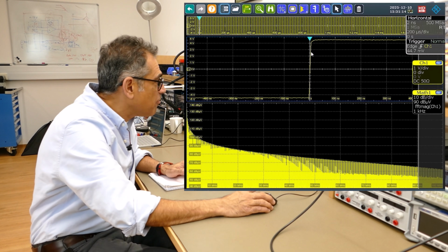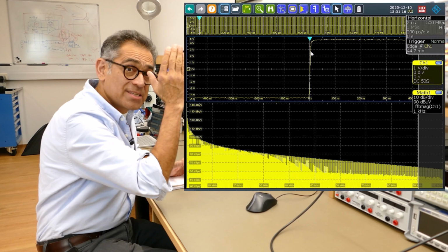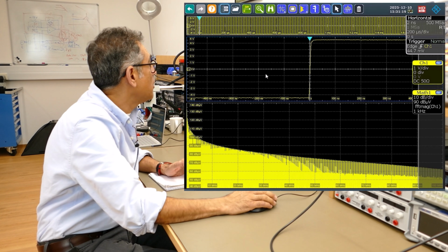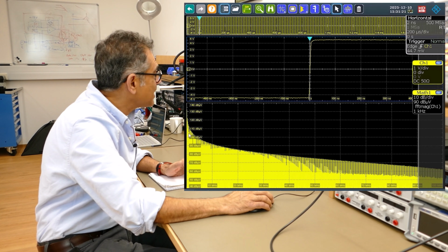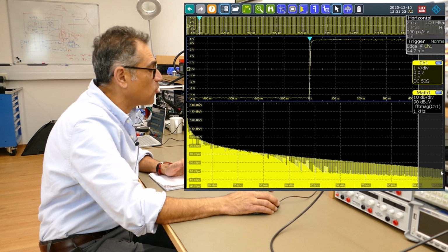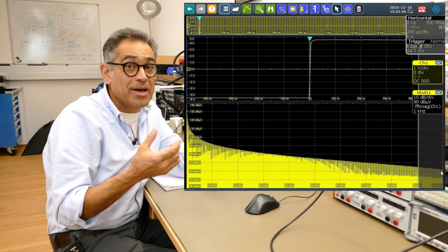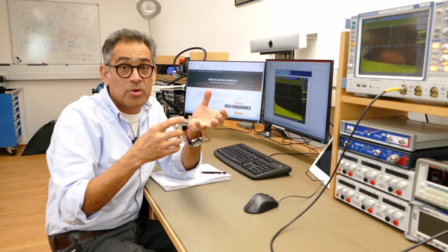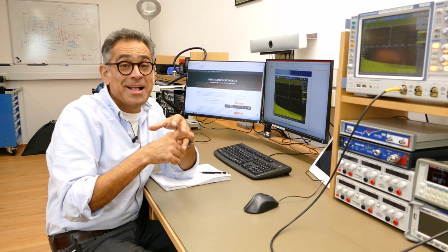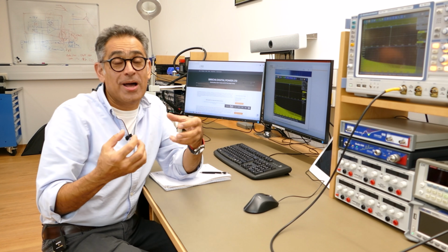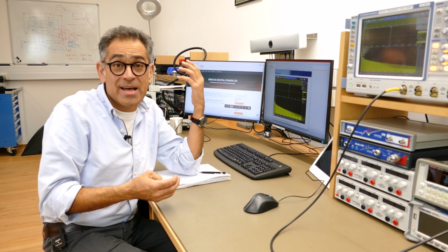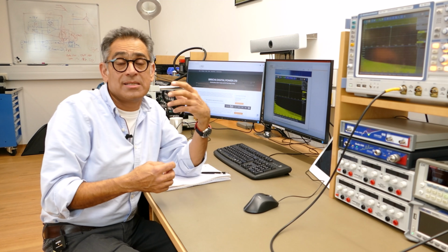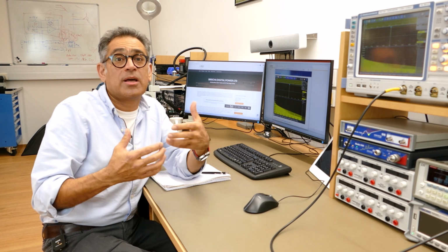This is now a very sharp edge, 5 nanoseconds is what it takes to move from -5 volts to +5 volts. And of course, there are all these spikes all the way up to 100 megahertz, and it is these high frequency components that will couple with capacitances and inductances, and that is why your power supply, even though it might be switching at only 100 kilohertz, if the rise time is fast enough, dI/dt, dV/dt is large enough, the noise will couple with other parts of the circuit.